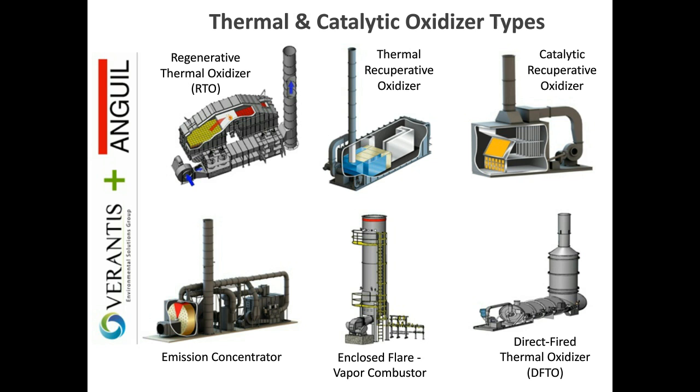The one in the bottom right-hand corner, and then the one in the bottom middle, which is our direct-fired thermal oxidizer, and then our enclosed flare/vapor combustor. I'll talk about these two as if they're the same technology. They're a little bit different, but for the purposes of this presentation, they're very similar. And they're also the opposite of the RTO in terms of thermal efficiency, where the RTO is designed for relatively larger air volumes and fairly dilute air streams.